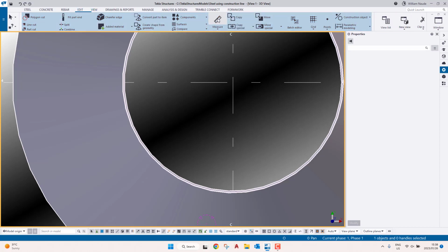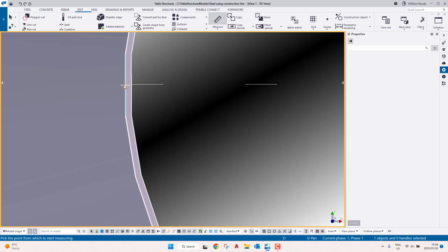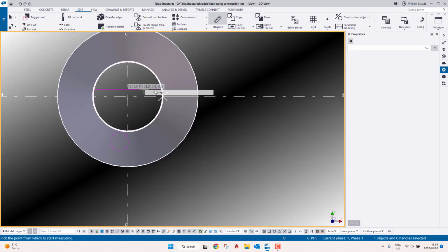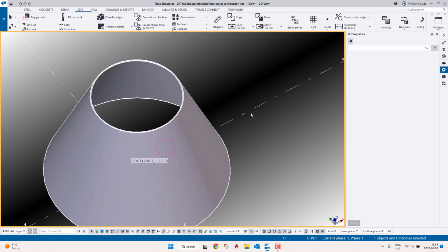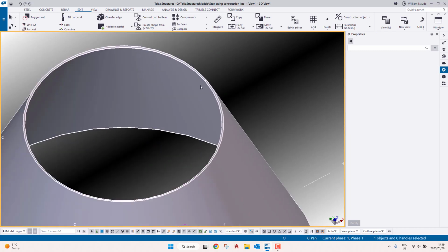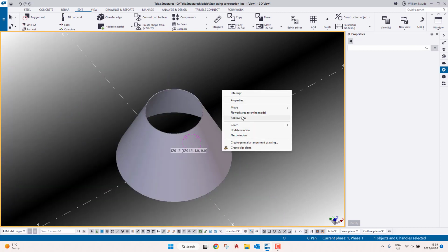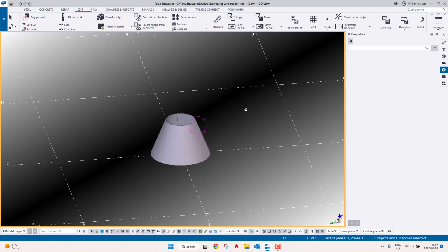So then we have a cone that has a total OD at the top. So edit, choose measuring tool. Originally this would read, okay, it's a bit off, but 1200. So that's the OD of 1200, radius of 600. The reason it's 1201 is because I didn't click it exactly in the middle. I chose a further point. So there we go, we have a radius. This is our cone.